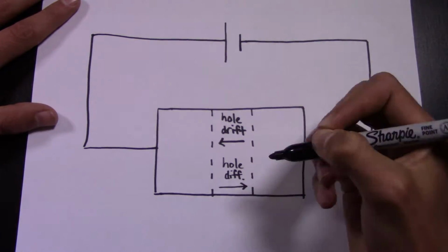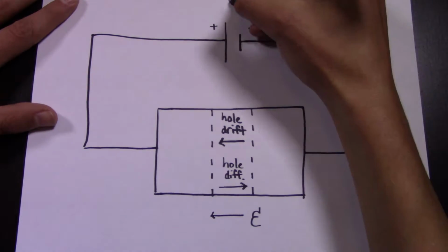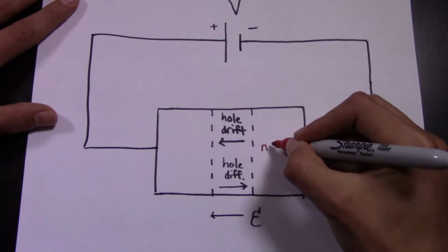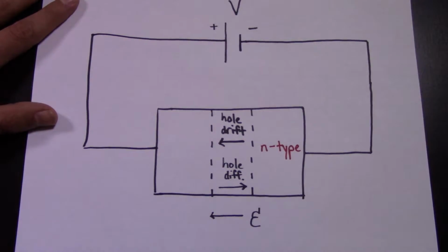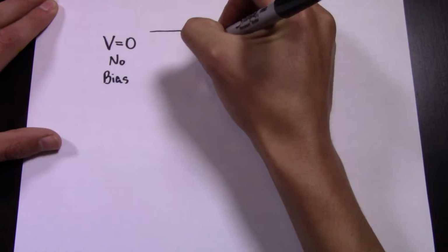When the P-type material is placed at a higher voltage than the N-type material, the diode is in forward bias and carriers overcome the internal field of the depletion region to diffuse, which sets up a current from the P side to the N side. Now that we've seen how a diode looks, let's delve into its band diagram.